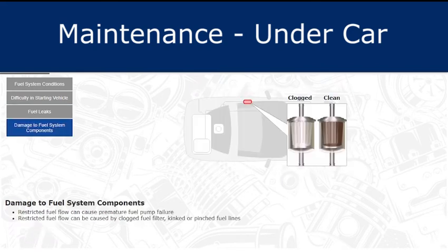A clogged fuel filter restricts fuel flow, adding more strain to the pump and contributing to premature fuel pump failure. It is also likely to cause engine performance concerns. Kinked or pinched fuel lines are other causes of restricted fuel flow.